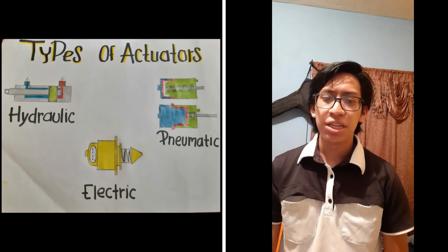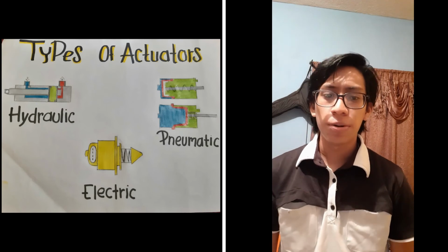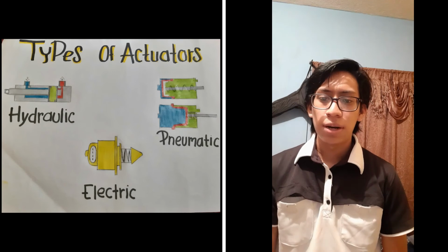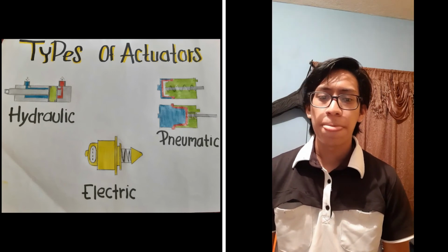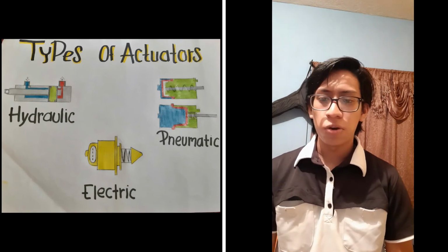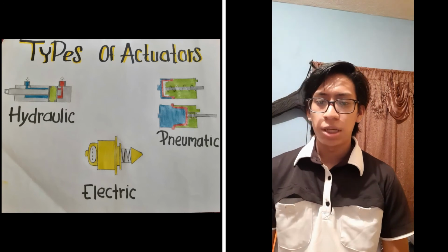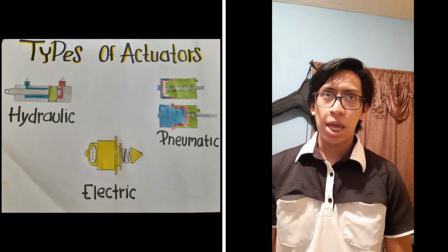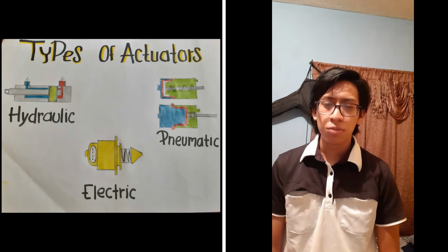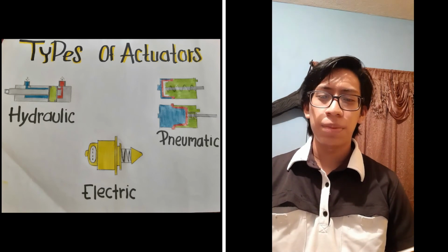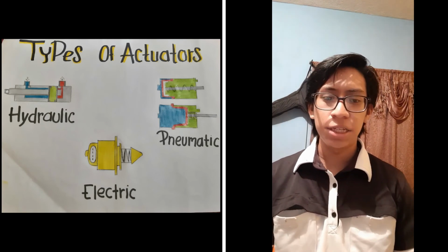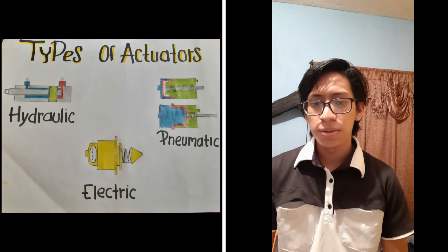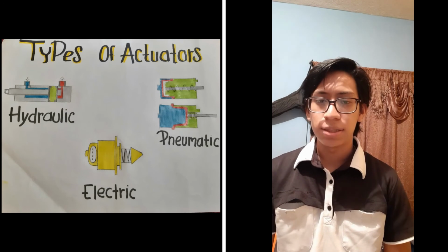Another approach is an electrohydraulic actuator, where the electric motor remains the prime mover but provides torque to operate a hydraulic accumulator that is then used to transmit actuation force, in much the same way that diesel engine hydraulics are typically used in heavy equipment.